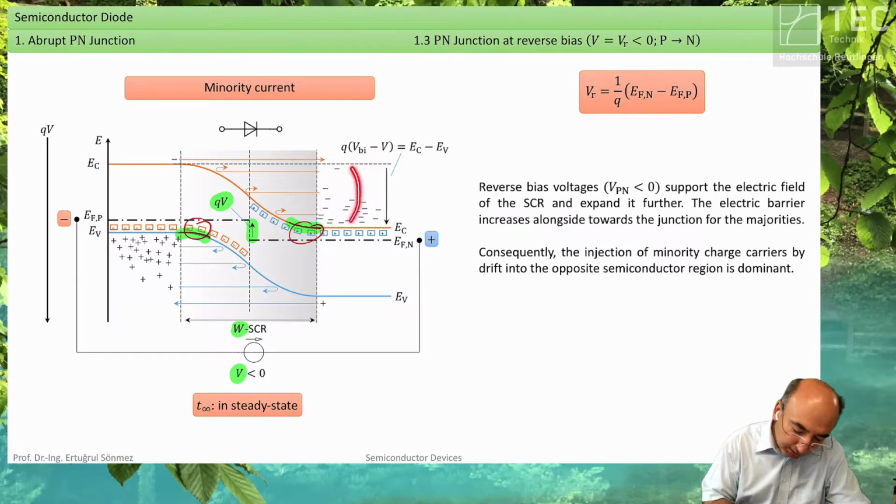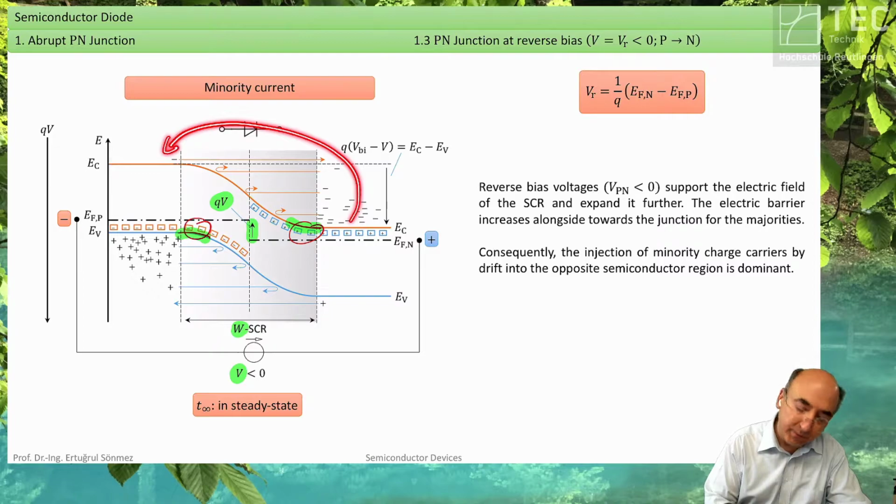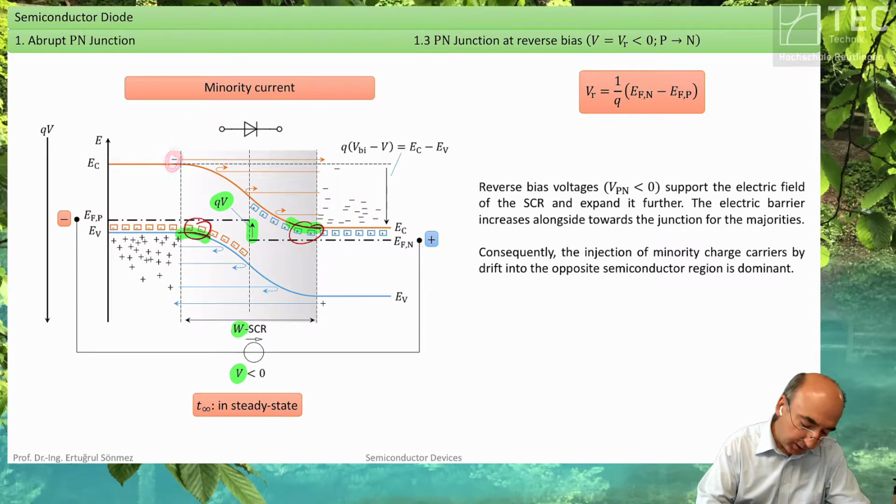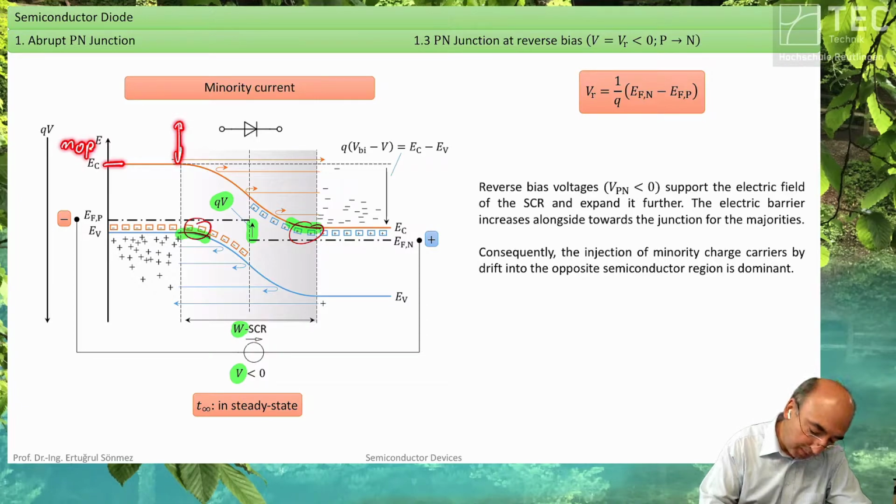If you flood electrons in this area, you change this minority carrier concentration, you inject a delta N. What have we learned about this injection? We learned that this concentration, which is not N0P, it is above it by delta, diffuses away.